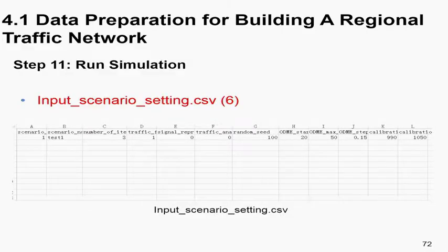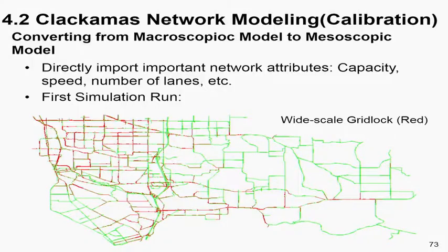Import scenario setting. To be familiar with this import scenario setting, you need to understand the number of iterations, which is essentially the number of days, the different traffic flow models, different signal representations, and how to select the different random number seeds. Once you go through these few parameters and get yourself familiar with this input scenario setting, then you can go on to perform a more advanced OD demand estimation.